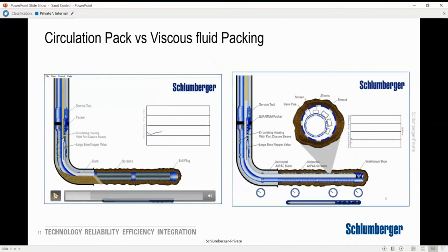As soon as your slurry, a mix of brine and sand, enters the open hole section, it starts to settle on the bottom. The industry calls it the alpha wave, or the first wave. The sand settles to the point where the channel is tiny enough that your fluid flow is turbulent, so the sand will not settle anymore and will be carried to the wider areas.